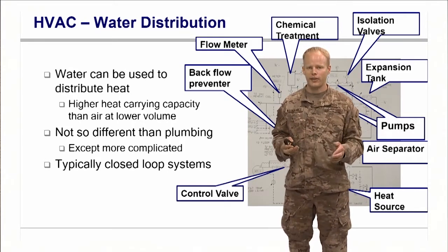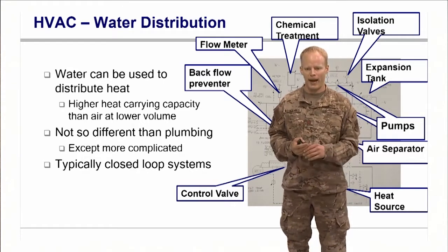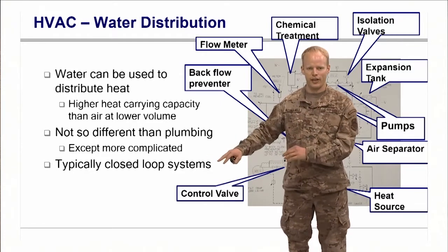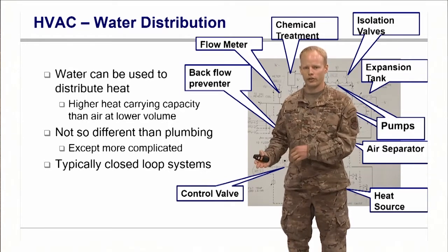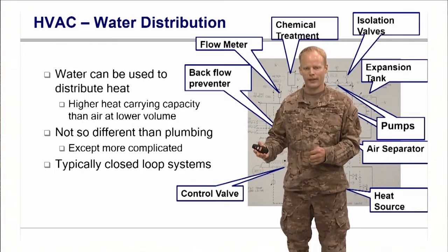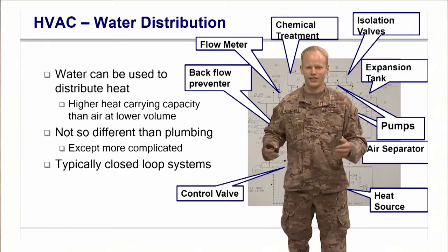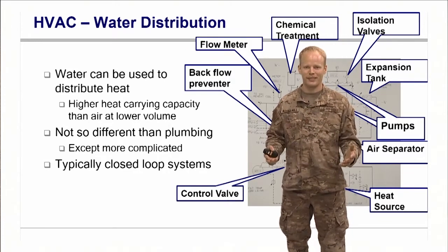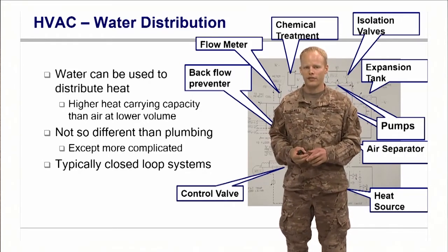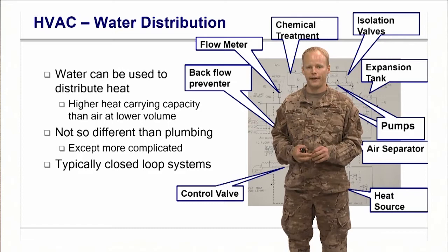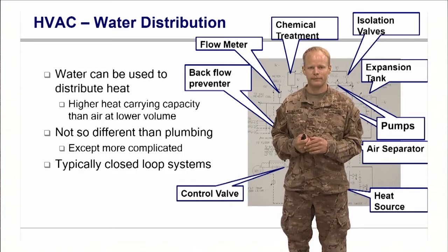There are some systems used in the past for cooling where, rather than returning the water back, they would use it and then discard it, because they figured it would be more energy efficient if we just treated colder domestic water or colder groundwater, cooled it a little bit more, and then once it warmed up, we just got rid of it. However, that is not water efficient. If you're in a place that has a lot of water, it could be more efficient for you, but I believe by UFC, it is not condoned. If you're in Phoenix, water is extremely valuable. That is not a very good option for you.